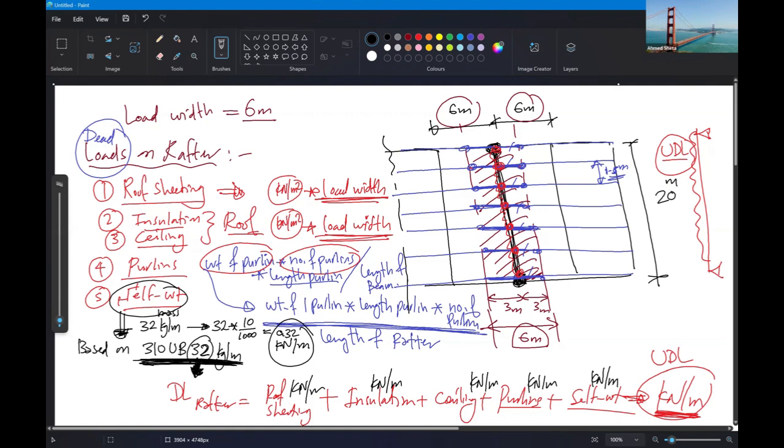And the weight of all the other materials, is that in the standards? Yeah, all other material in the standard 1170. 1170.0, 1170.1. Okay. 0.1 for the material, the permanent load or dead load and live load. This one for the load combination, and 0.2 for the wind.